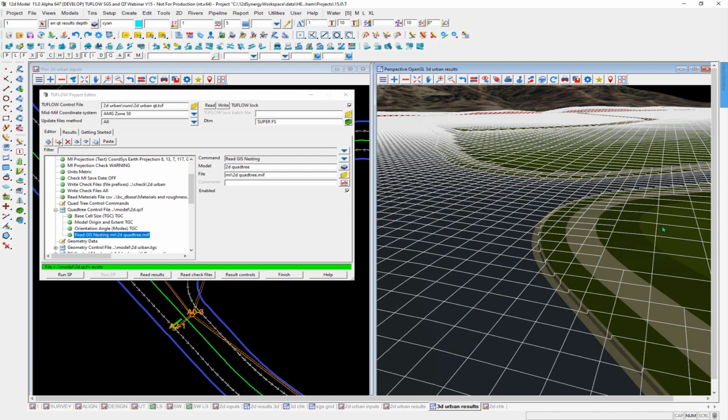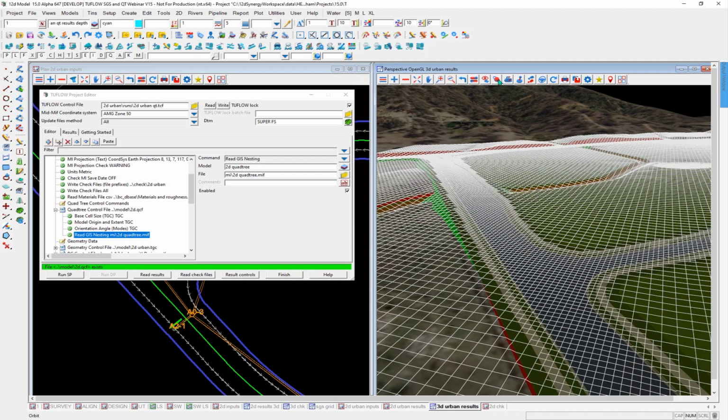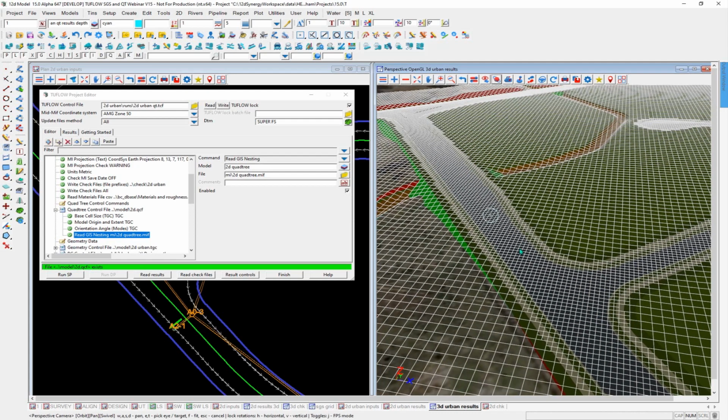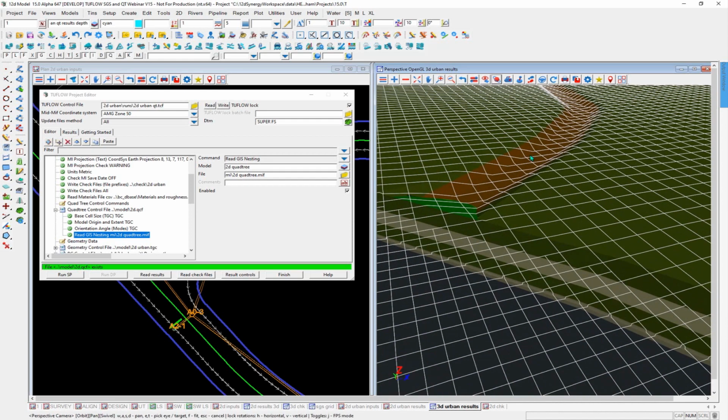We've got our basic base. Here's the 1 meter cell size. Here's our refinement, where we've gone down to a level 2 refinement. We have SGS turned on, so we have better defined edges for the flow. And if we go back and start looking at our channels, grab my orbit controller, you can see that we well and truly get an excellent description of the shape of the sides and the storage in the bottom.